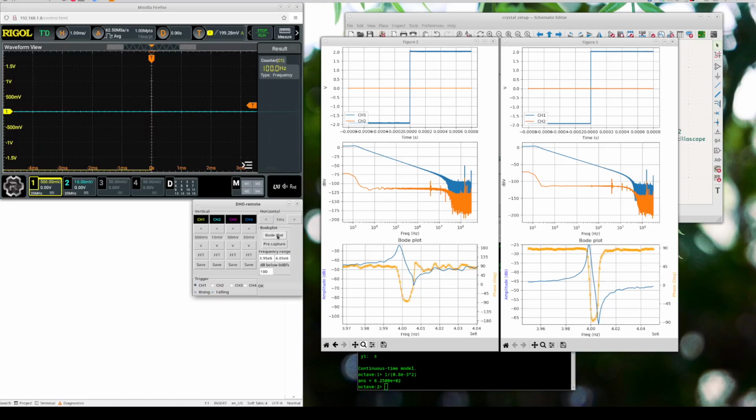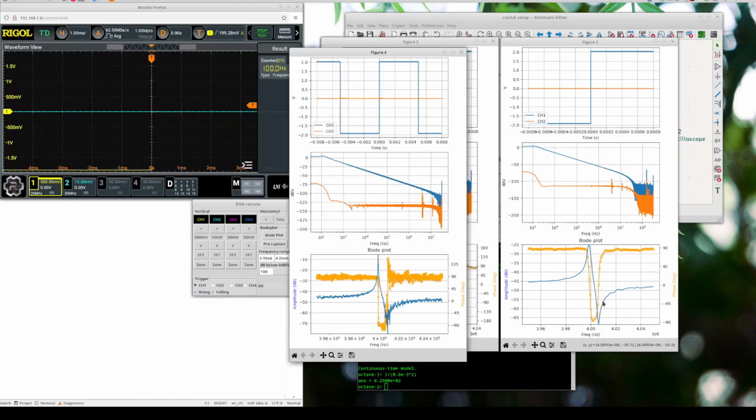And I do a Bode plot again. I still display the same region here, by the way. What you now see is that here there was a square wave, but now the square wave is limited by my generator. So now I see the edges of the generator. And what the FFT does is it says that at the end of this interval, it just repeats again.